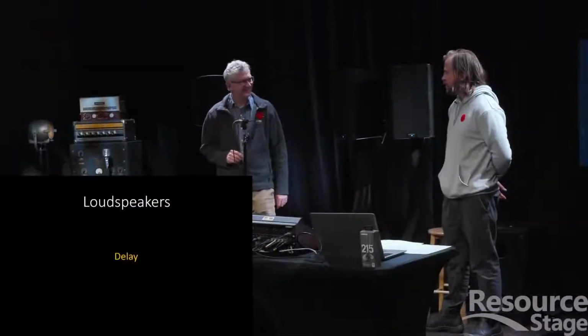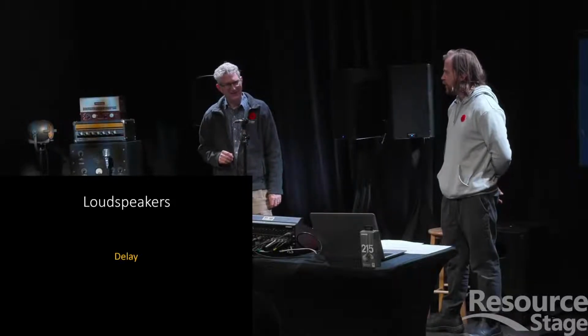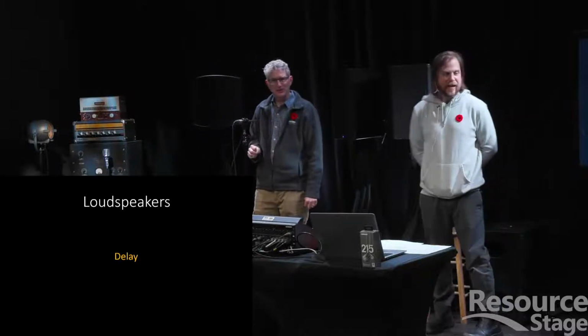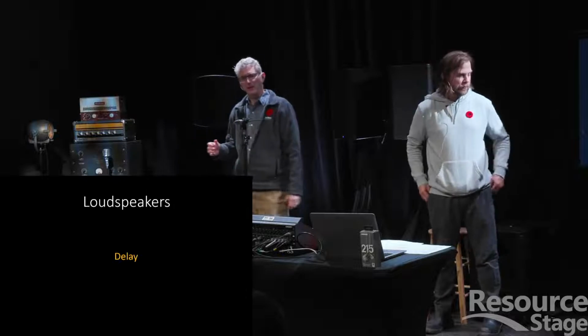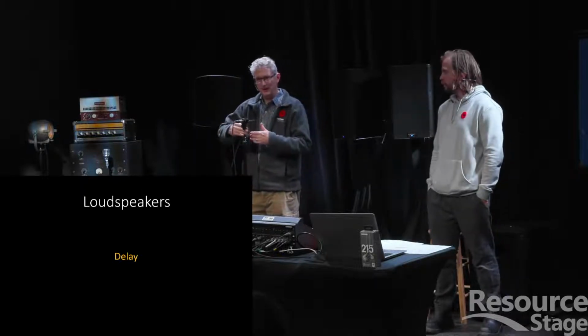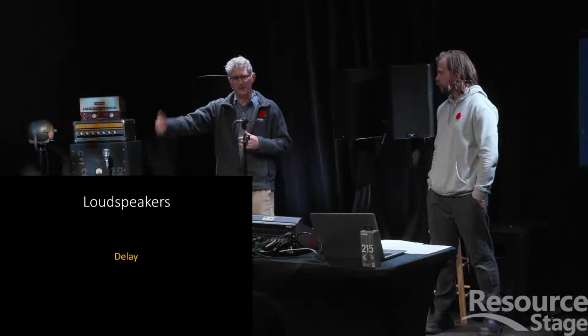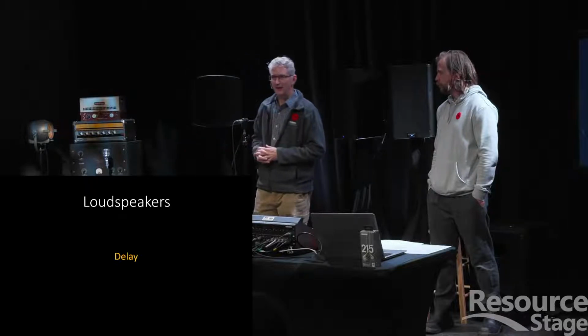Don and I were talking about this before because it could lead into its own seminar. We use delay. When we talk about delay, what we're talking about is actually delaying the audio sound going to a particular loudspeaker. A good example is where we've got a fairly long room, with one loudspeaker up near the front covering the front half of the room, and another speaker towards the back covering the back half of the room.